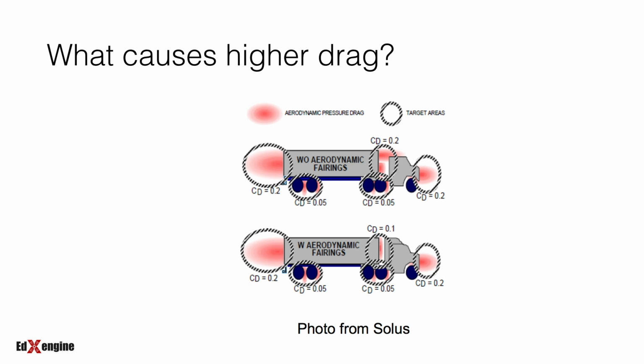Now, how to reduce the drag coefficient? Well, to do that, we need to first look at where the drag is high. Drag is caused by the presence of high and low pressure regions in the fluid flow. With respect to a truck, with and without aerodynamic fairings, you can see the regions that are responsible for drag and where you can actually design and develop aerodynamic solutions.